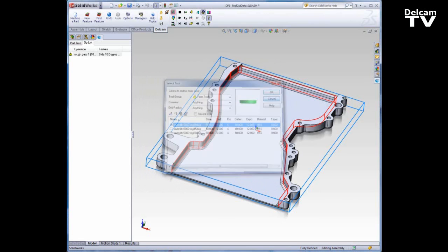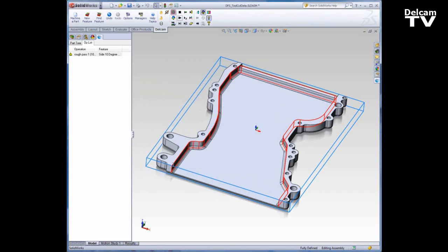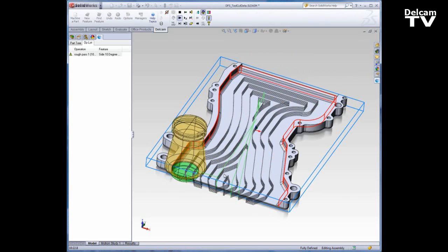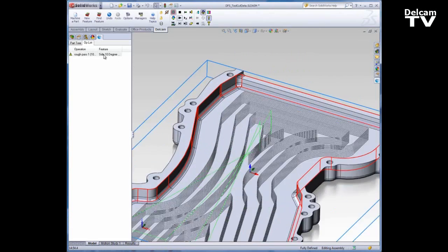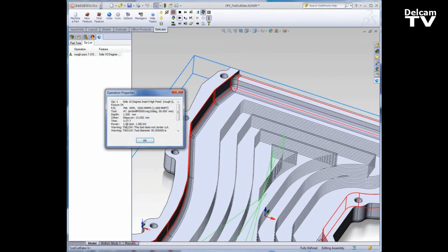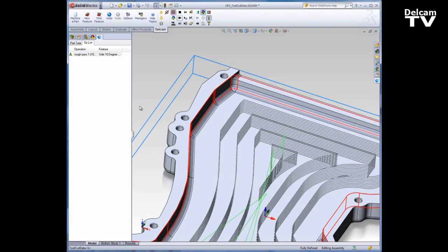Again, this is an aluminum part, so let's take a look at the tool path. Again, now even more step downs. Fortunately, one more time, our overall depth does divide equally by our step overs, so I expect to see exactly 1.5 mm in that 15 mm step over, the 796 RPM that we saw in the feed and speed overrides. Let's change the material of this file and see if that behaves as expected.